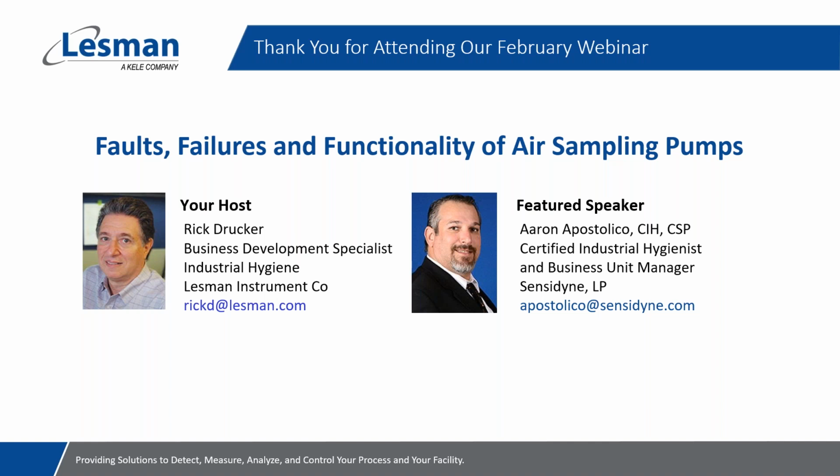Next question. How do you know what your back pressure is as loading occurs? Does the pump display back pressure levels? So our Gill-Air Plus pump does. It's the only pump in our line to actually display what that is. It's most certainly a benefit to have, and one of our user features. Most other pumps, and I'm not even sure if other competitor pumps display back pressure. If you don't have that, really the only way to check it during a sampling event would be to use one of those calibration panels that I showed you in the earlier slide that has the Magnehelic gauge on it.